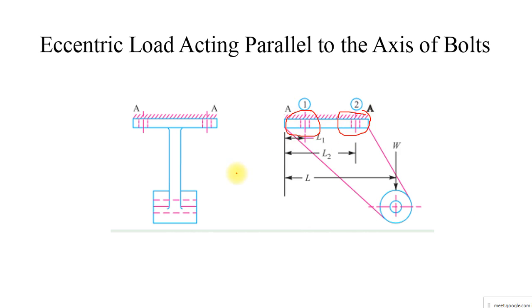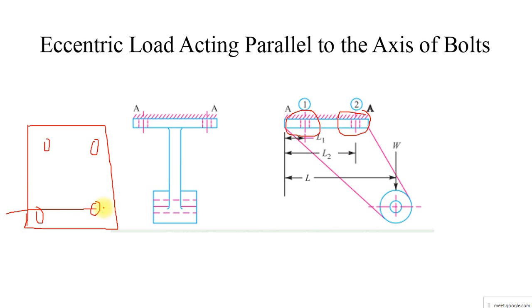If it is going to be a wall bracket, it can be fixed in this particular manner. So I have a bolt and nut here, a bolt and nut here, a bolt and nut here, and a bolt and nut here. If I make a cross section, I am cutting it like this, or cutting here like this, so as to have the sectioned view of a particular wall bracket.